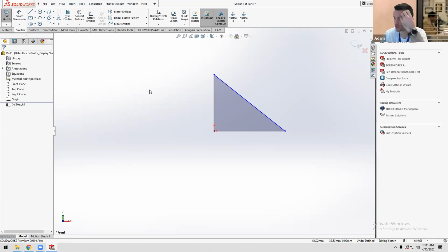And I'm going to show you the shortcut, which I love to use, and it saves a lot of time, which is to right-click on my mouse and drag it a little bit. So I'm clicking and dragging. Now, if I don't drag all the way to the outside of that, it's not going to do anything. But if I drag it and keep going out, it changes to that tool. So I can do that to make lines or dimension stuff, or if I do it twice, it toggles it off.